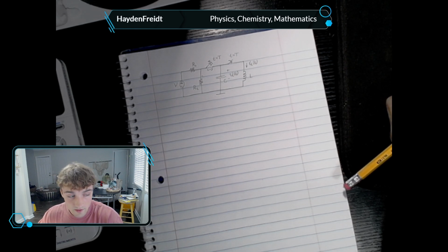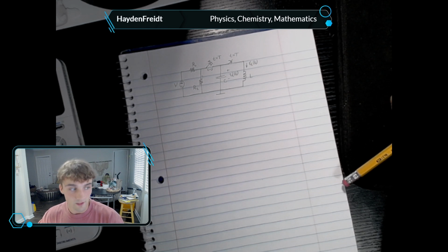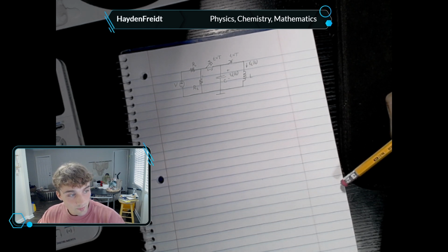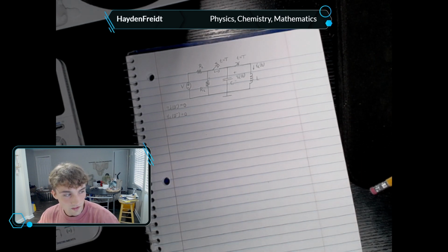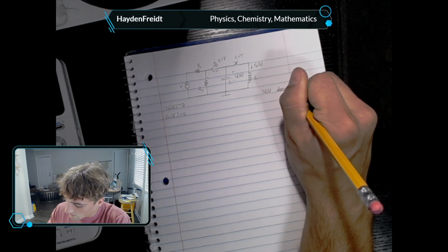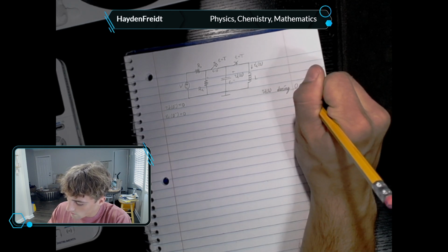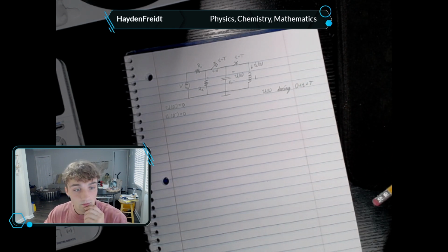Two resistors in series give us a voltage divider, defined by the voltage divider relationship, which you could define in other ways, but it's so common that it's worth remembering. So both switches are open and the circuit is initially at rest for T less than 0. At T equals 0, switch S1 is closed, but S2 stays open. After a very long time, capital T, S1 opens and S2 is simultaneously closed. What is Vc of T during 0 to T? That's what we're about to define right now.